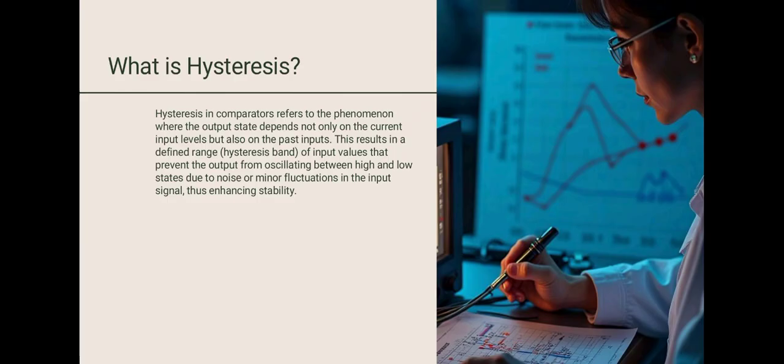Hysteresis and comparators. What is hysteresis? Hysteresis in comparators refers to the phenomenon where the output state depends not only on the current input levels but also on the past inputs. This results in a defined range, a hysteresis band, of input values that prevent the output from oscillating between high and low states due to noise or minor fluctuations in the input signals, thus enhancing stability.